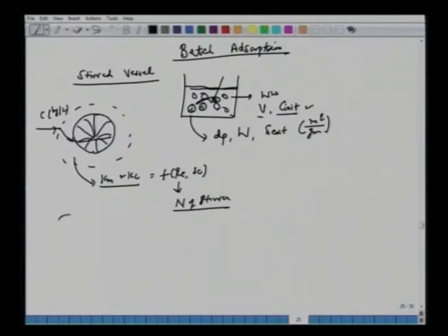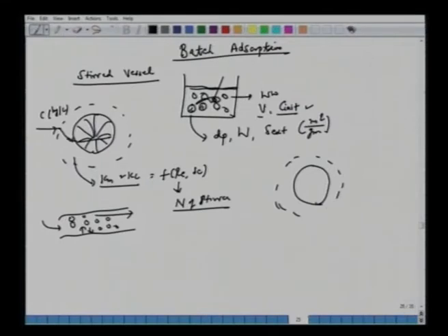If you look at one pore, the reality is that the species get inside and then adsorb and desorb at the wall at certain rates. But we are saying that this is very fast kinetics. There is no gradient here. So at any time, if you look at this adsorbent surrounded by the solution, to start, say this concentration is Y0, and it's a fresh adsorbent, so there's no concentration here.